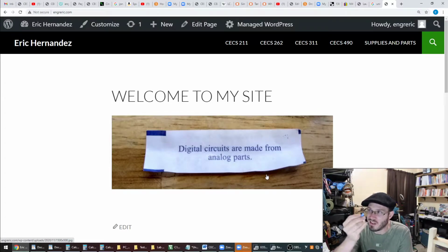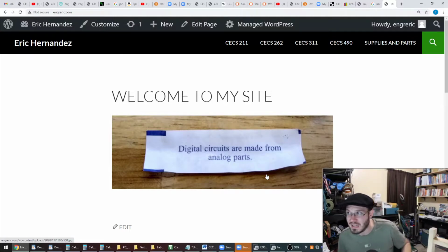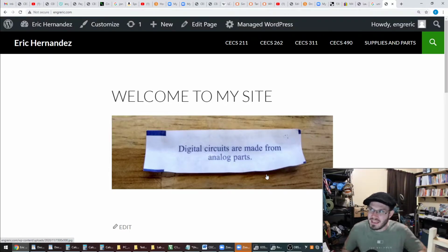When a capacitor has some resistance, we call it parasitic resistance, and parasitic inductance, because they're not things we want. The same for a wire: if we have an ideal wire, we would like to treat it as 0 ohms, but it has a little bit of resistance and inductance, which we call parasitic inductance. I think those are what make the analog world a little more difficult.